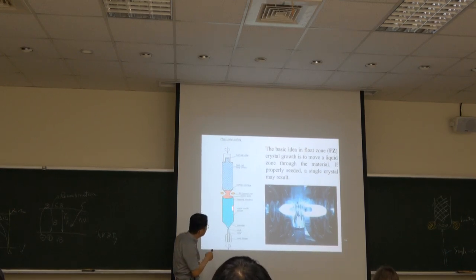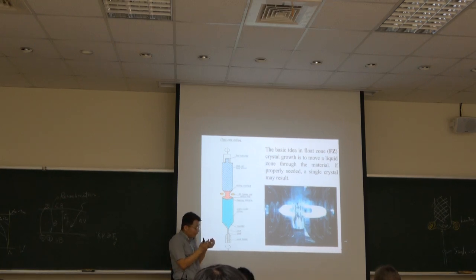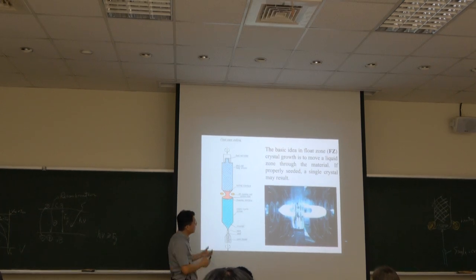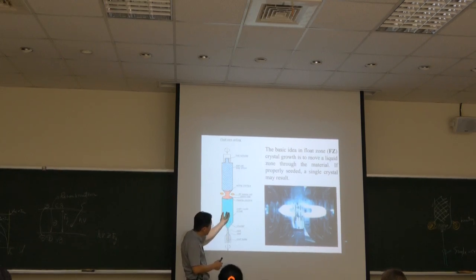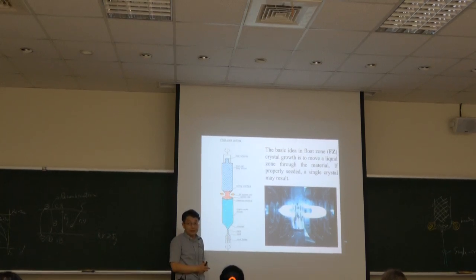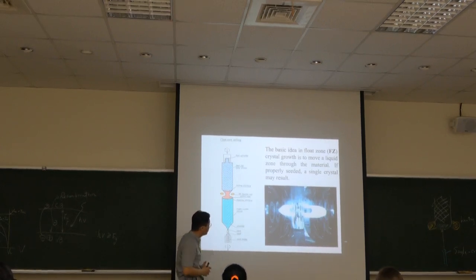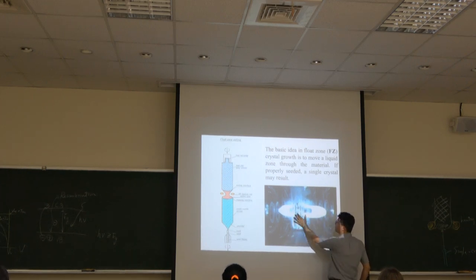So finally, because here is a liquid state, the liquid state atoms will progressively attach to the single crystal seed, and then grow. Growth happens when they pull away, drop away from the liquid state of the silicon, and then become solid, which will form a single crystal chunk, an ingot. So this is the case for germanium.